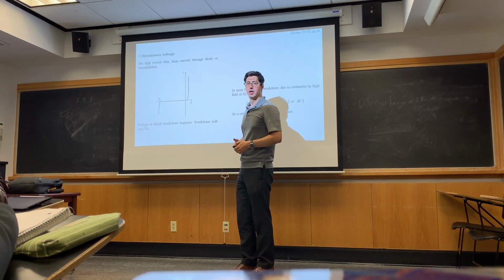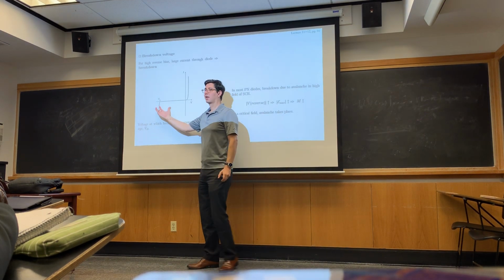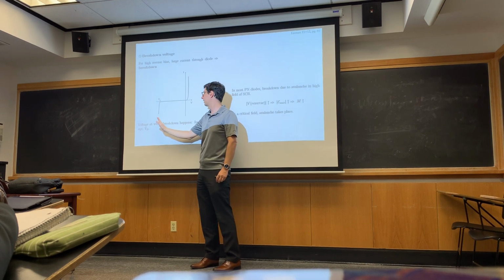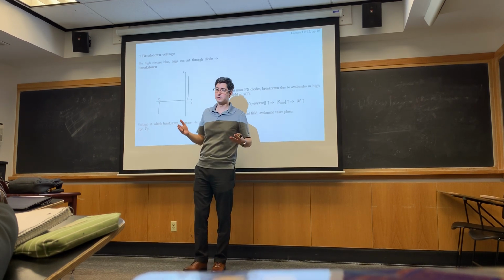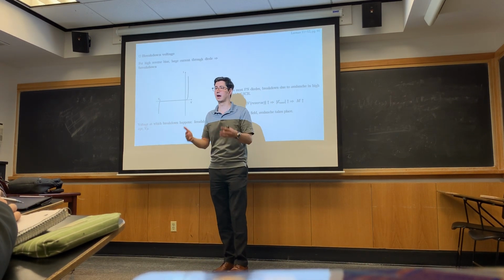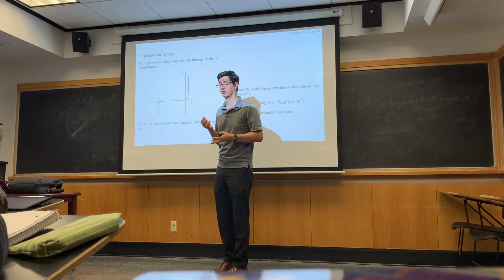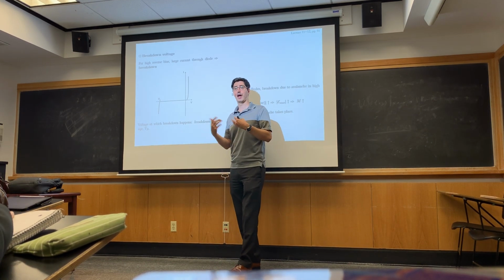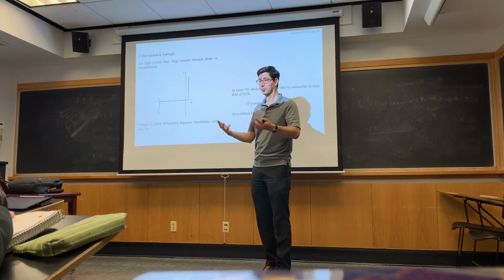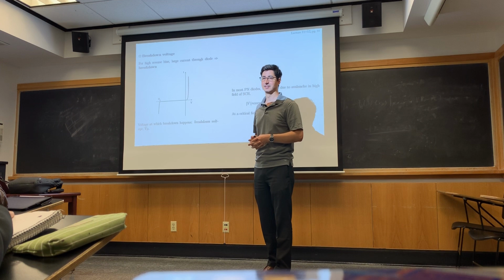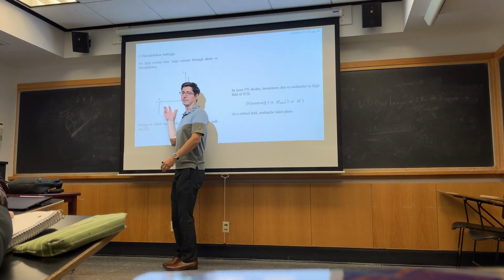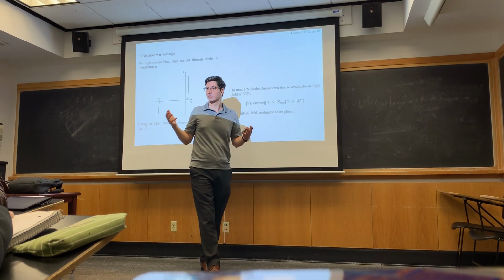Now, of course, when you want to use this, your current is increasing really quickly, in both forward bias and reverse bias. If you let that current increase to whatever you want, well, you're going to burn up your device, it's going to die, you're going to start burning plastic if you're using discrete components. If you haven't had that opportunity in your life to burn a discrete component, you should play more around with discrete components and max them out. But this diode might be rated for some max current.